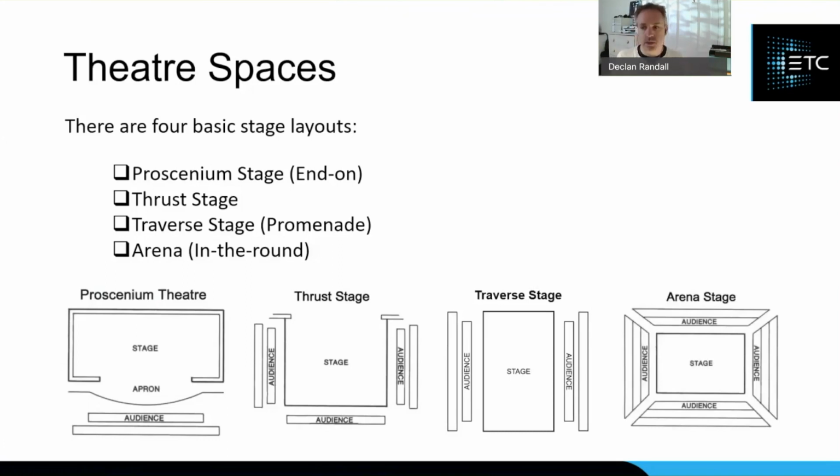The principles will apply to either. And what we're going to have a look at, casting a quick eye as a quick summary over sessions 1 through 4, is how you achieve your lighting objectives for each of the 4 main spaces. So your 5 objectives, if you remember from the previous sessions, would be visibility, revelation of form, mood, composition, and information. And it's the combination and probably slight reordering of these objectives that you would do for each approach to each of the different layouts.